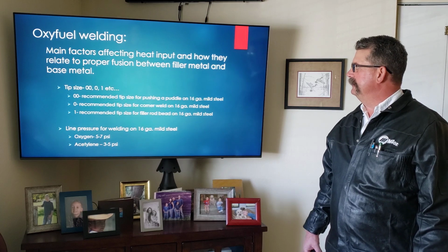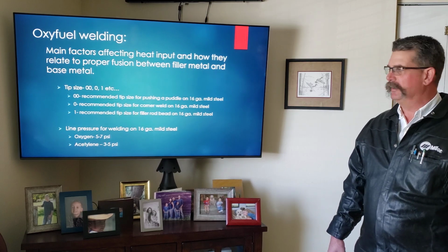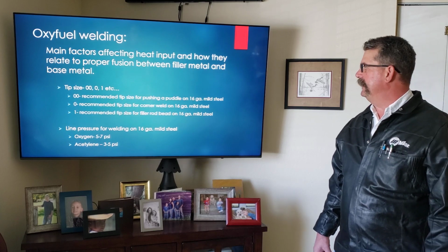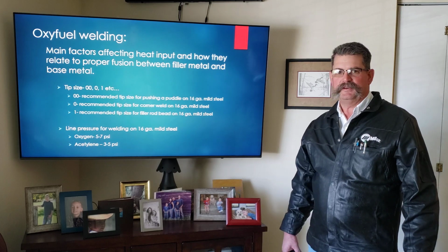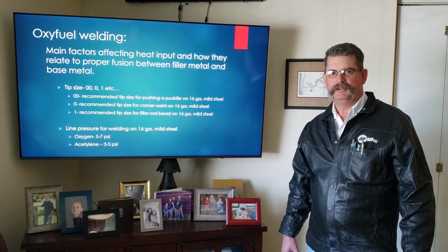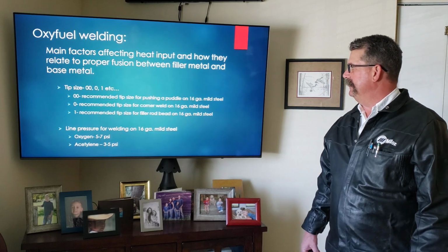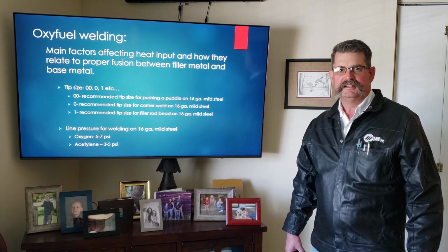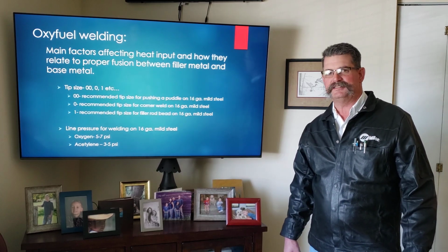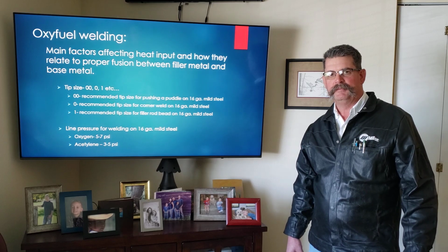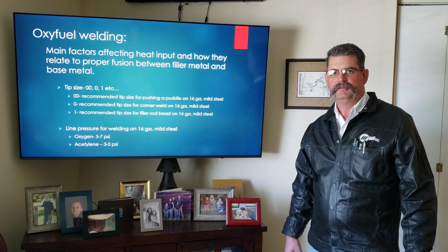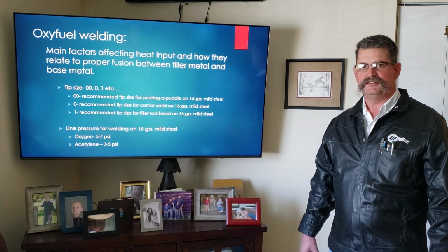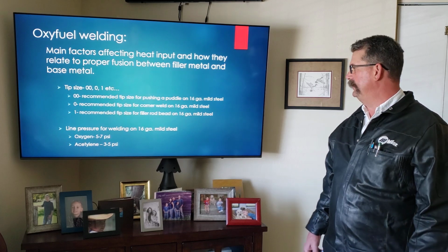We would talk about what main factors affect heat input and how they relate to proper fusion between filler metal and base metal. To address those factors, we want to talk about different components of an oxy-fuel welding system. One of those things that I talk about is tip size within the class. Three main tips that I have students practice oxy-fuel welding with are a double aught, an aught, and a number one.